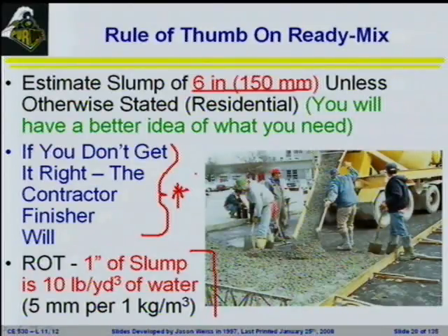And the real issue that I will point out, a lot of what we deal with, is variability from one point in construction to another. On a more commercial project, you'll have 10 trucks that are perfectly designed and one that has way too much shrinkage, and that's where you're going to get your cracks, or your scaling, and that's really what people are concerned about.